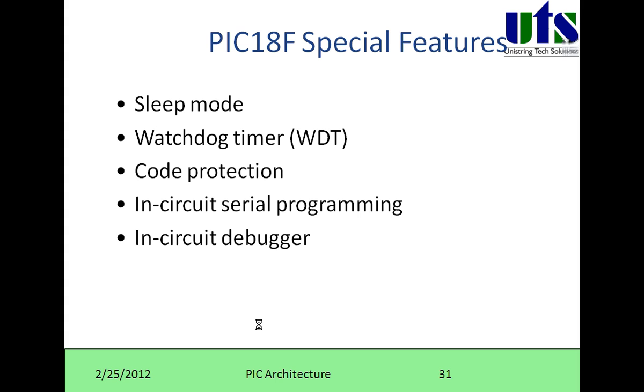Okay, and watchdog timer. Watchdog timer is one such feature which continuously monitors, continuously watches the memories. Whenever any memory overflow occurs, it will automatically generate an interrupt, that is called a software interrupt. Whatever overflow occurs will be generated using the watchdog timer. And there is code protection in the flash memory, and it has in-circuit serial programming, that is in-system programming, and in-circuit debugger. Within the circuit only we can see how the instruction is executing by connecting additional external in-circuit debugger protocols like JTAG protocols.